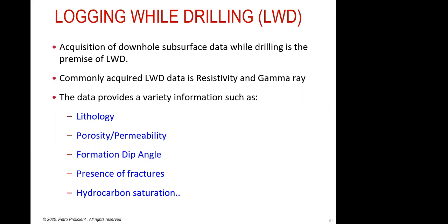The advantage that you have here is that these are the measurements that were traditionally done using wireline logging. So with the advent of LWD, you can now get all this information, and more than this, while you're drilling, without having to spend time for electric logging, which is a time-consuming process. So when you reach the section TD, you kill the well or you displace the well with a heavier mud, and then you go with a few logging runs. So that's a time-consuming affair.